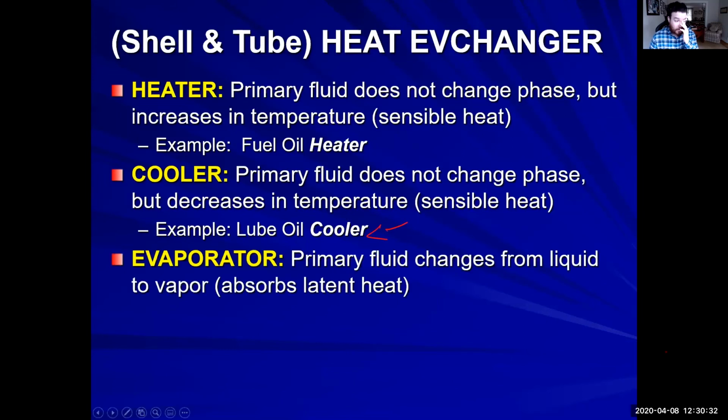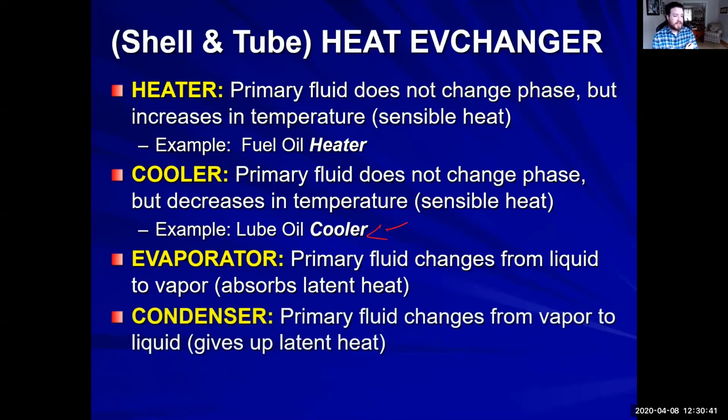Then we have an evaporator. All right, primary fluid changes from a liquid to a vapor, absorbs latent heat. And then we have a condenser, which is our primary fluid changes from a vapor to a liquid, and it's giving up its latent heat. All right.